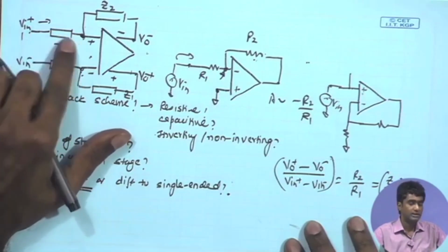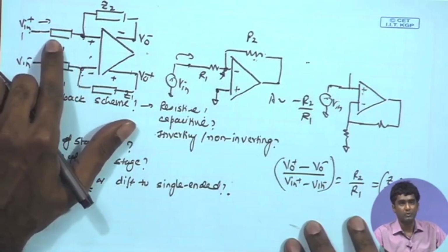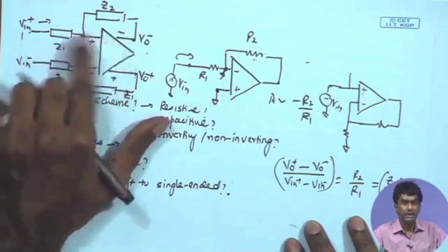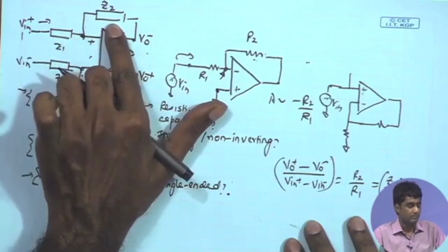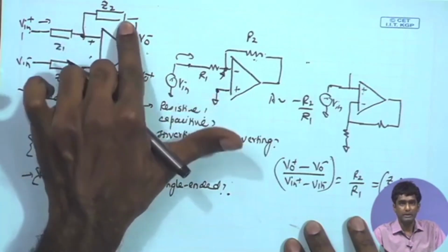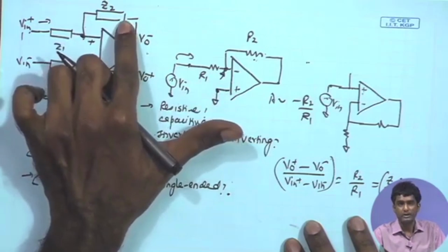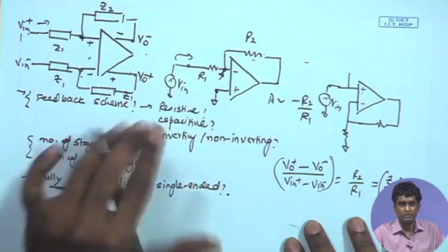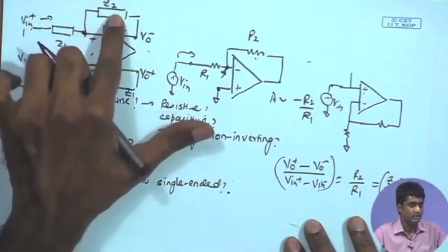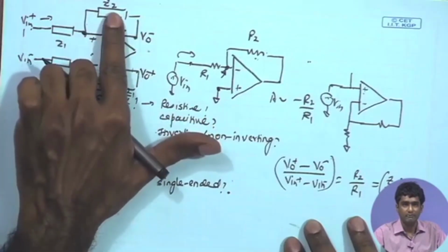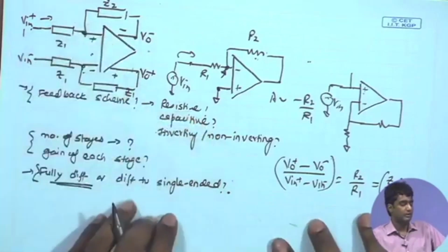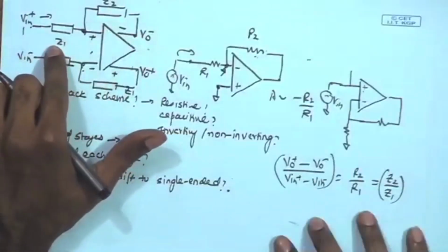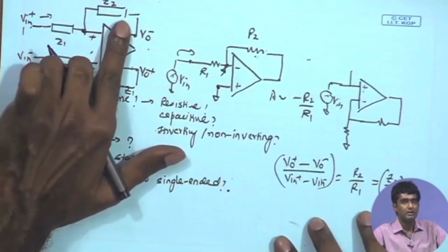The other thing is that if you use a large R over here, maybe 10 mega ohm, and you are trying to build a gain of at least 100 in this stage, then this one will be even larger. For 10 mega ohm, you will need 1 giga ohm over here to get a gain of 100. That will also create difficulty in realizing the feedback with accurate enough values or accurate enough ratio of R2 upon R1. So these two factors make the choice of R as the feedback element a bad one. Rather than that, we would go for capacitive feedback.